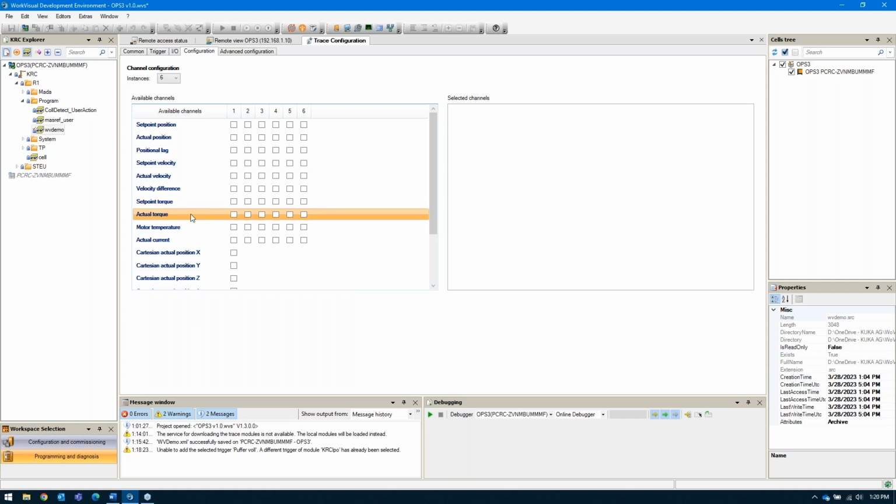Set point torque and actual torque. These are things that if you're having problems, say you're burning out motors for some reason on a particular wrist and you're not sure why, you can monitor these torques, and if you're getting spikes and peaks in certain areas and you're not sure why, you can check the positional data compared to these torque values, and you could be rubbing on something or just bad programming, and you need to smooth out some of your corners in your programming.